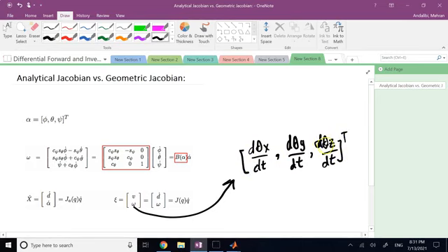Absolute angles, extrinsic rotations. But most of the time, these angles are not how we measure the orientation of the end-effector. And so when we take a derivative of them, then the omega they give us is also not this omega, it's a little bit different, right? The question is, if we change this omega to be, let's say, the omega coming from Euler angles, then how does my Jacobian change?